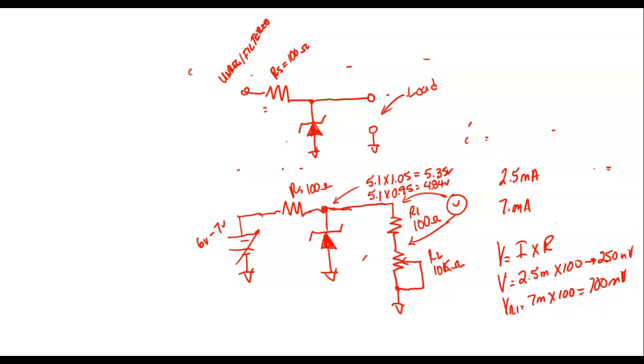So now I know I can take my voltmeter. So let's switch over. So what's the first voltage we want to do? Zener part number. Draw the circuit. Have the instructor check your circuit. Set the 10K to the mid-range. Adjust the trainer's power supply to set the input voltage to the minimum value given. Okay. So what we're going to do is let me switch back over to my camera.